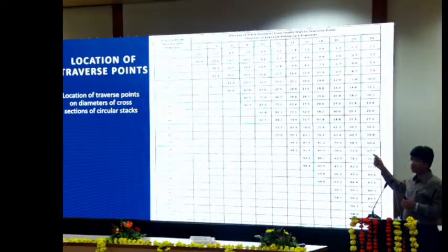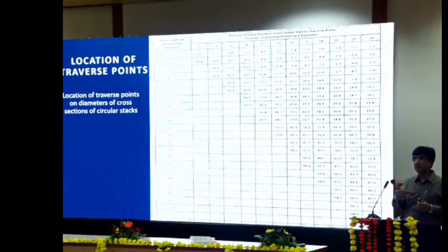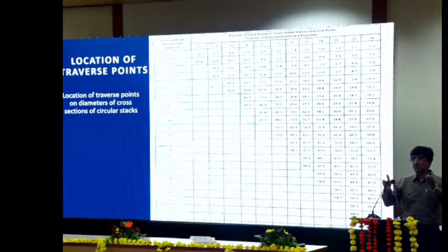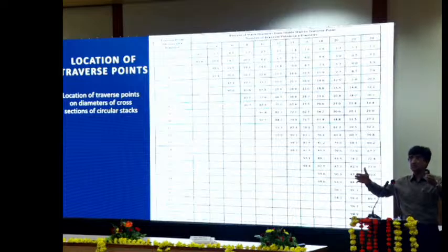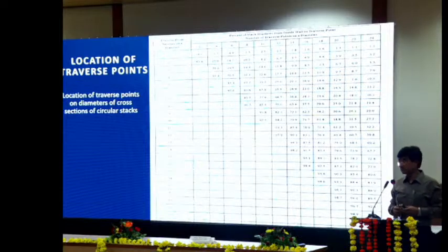And then there is a flange joint of the order of about 10 inches. So the probe length has to be considered, where these points are very relevant. If it is half a meter plus another 1 foot, 12 inches, you see 60 centimeters of the space has been taken away by the wall only. So you are not actually going inside the stack to collect the sample.